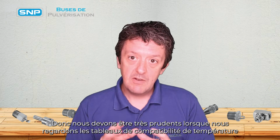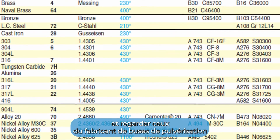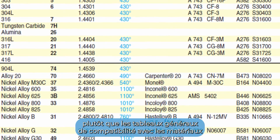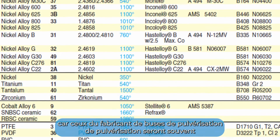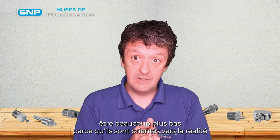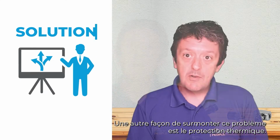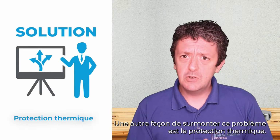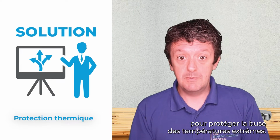So we have to be very careful when looking at temperature compatibility charts and look at the ones from your spray nozzle manufacturer rather than general material temperature compatibility charts, because the ones from the spray nozzle manufacturer will often be quite a lot lower because they're geared towards actual spray nozzles rather than all the more general components. Another way of overcoming this problem is through heat shielding. We can look at various heat shielding solutions to actually protect the nozzle from the extremes of temperature.